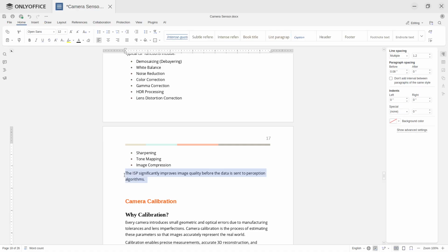So the thing to understand is that whenever we have a camera sensor, we will have a camera sensing pipeline. After the sensing pipeline, you have something called a perception pipeline. The goal of the sensing pipeline is to make sure that the output data is so correct, so good, that the perception modules, which have machine learning algorithms that do object detection, object tracking and all those kinds of things, find it easy to do object detection and tracking. But if the output of the sensing itself is not correct, then the perception will not do a very good job. Right.